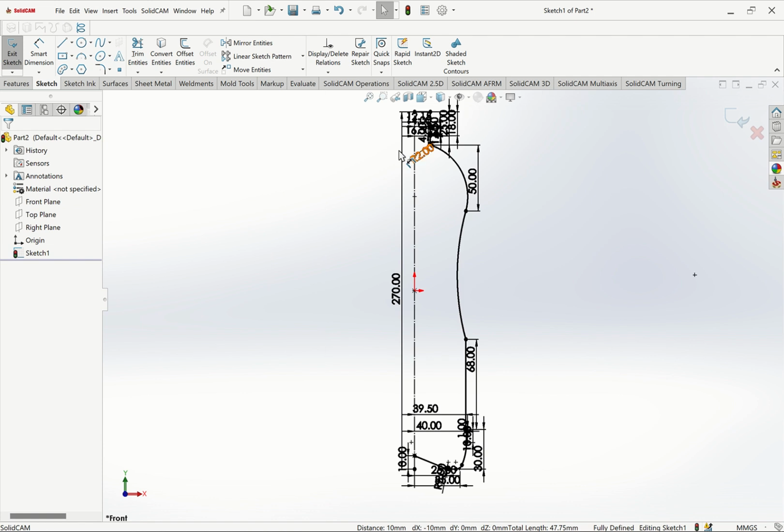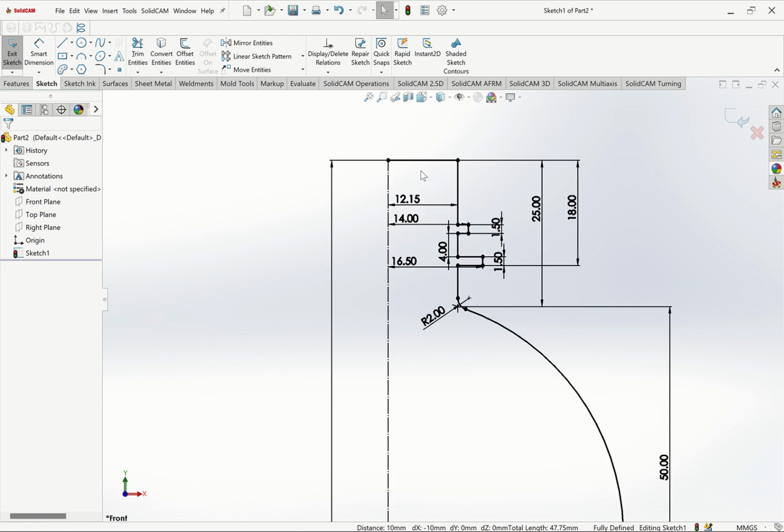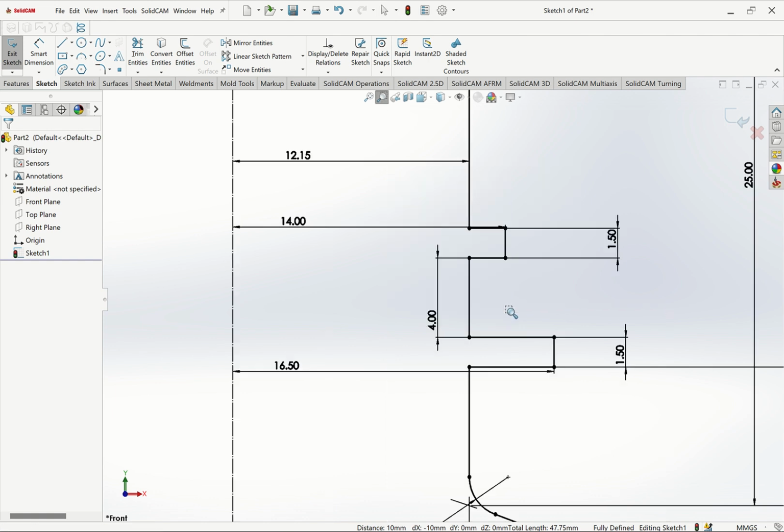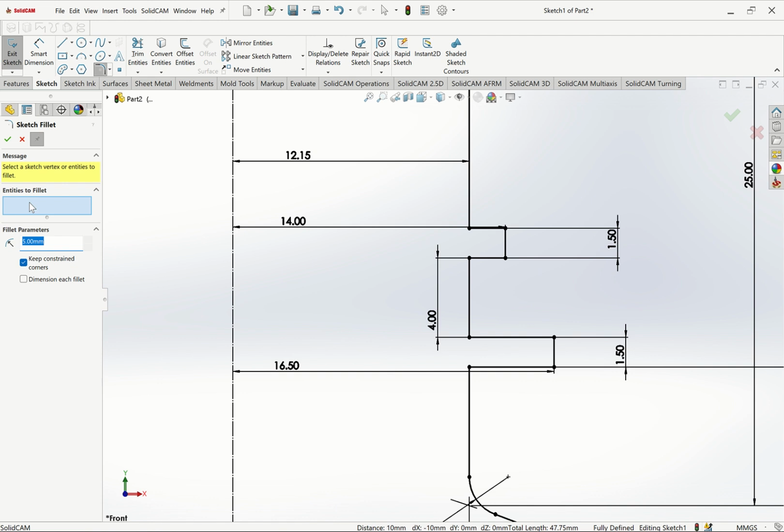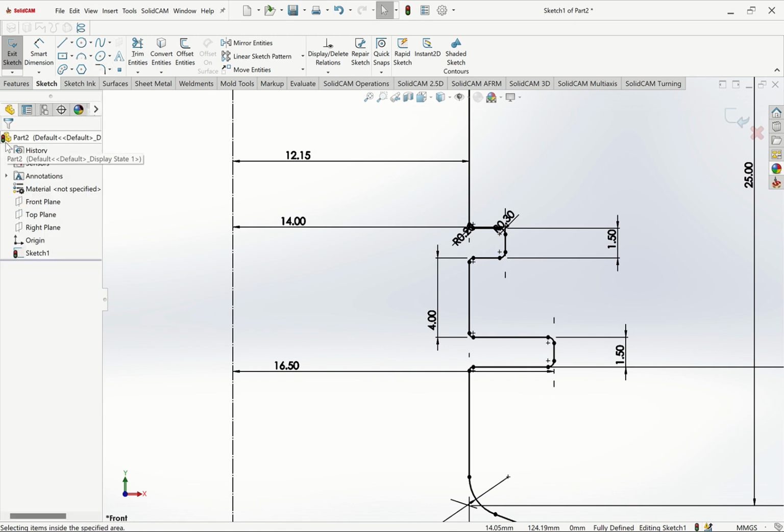Okay. So once I have done this one, I want to fillet. Yes. Fillet where the sharp edges. Fillet 2 where the sharp edges. These are points of weakness. Okay. Minimize points of weakness. Okay.